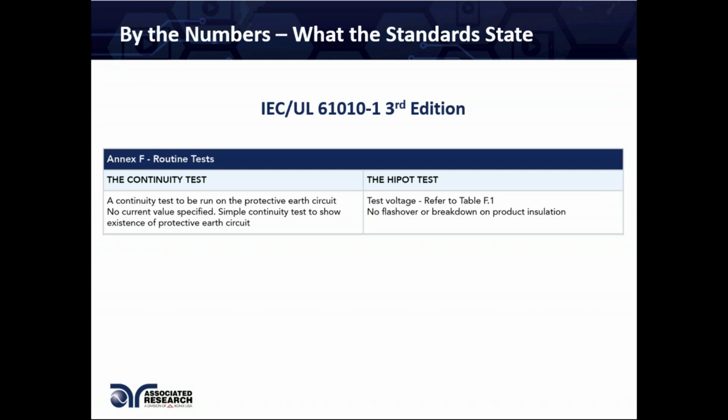Before we get into more details about the ground bond test, let's look at a requirement for a ground continuity test. In the previous examples from the standard, we looked at requirements of a ground bond test. Now we're looking at continuity tests, and most commonly continuity tests are required as end of production line tests, because a ground bond test is more commonly required as a type test. When you're designing a product, you are required to perform a ground bond test for say 60 seconds or something, and